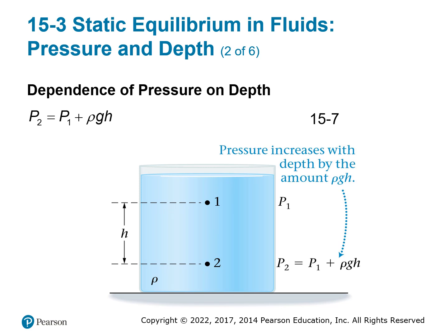Depth has an effect on pressure. The deeper you go into a fluid, the more depth, which means a higher pressure. Same equation as before. So if you wanted to compare the overall pressure at point 2, which is down here towards the bottom, you would take the pressure at point 1, which they have put here, and add the pressure due to the density of the fluid multiplied by the height.